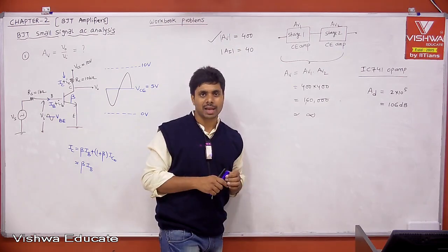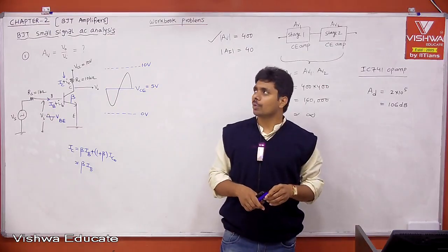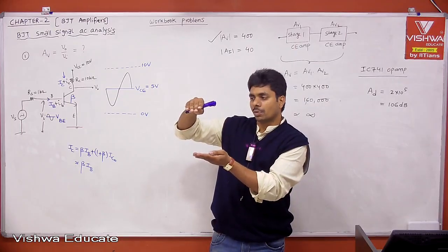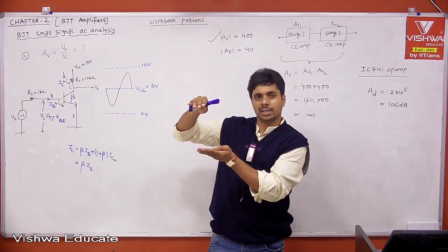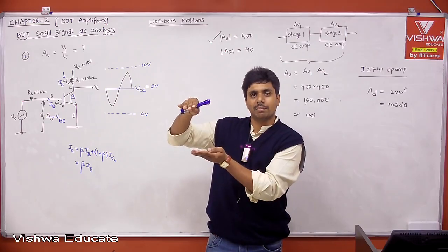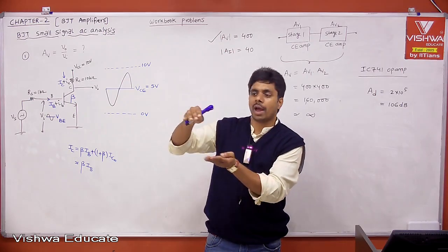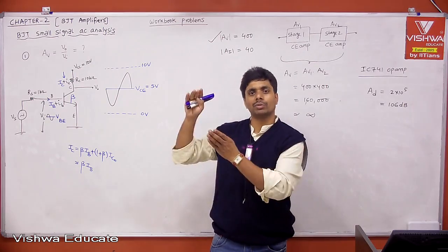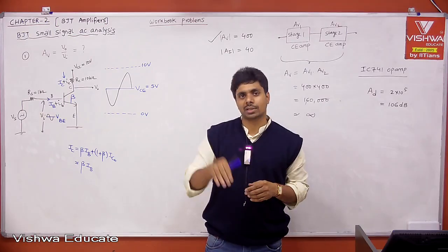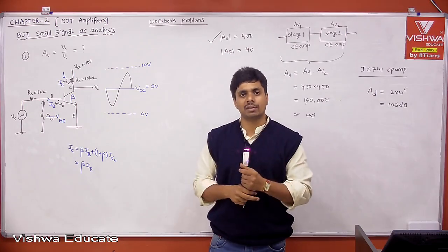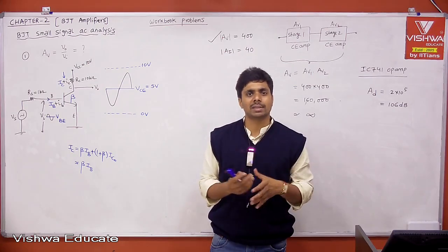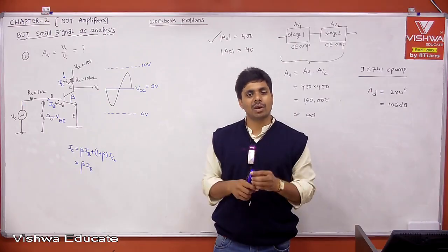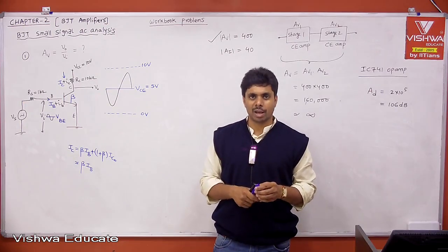Let me give you a small practical example. Remember, the power supply we get for our home applications is 230 volt RMS. That is nothing but an AC signal of 230 volt RMS. Let us say you are giving that to a fan, an 80 watt fan. When we give 230 volt RMS, the current it takes to get the mechanical power of 80 watt is in the order of less than 1 ampere, right? It will be in the order of 0.4 ampere. Your current will be in the order of 0.4 ampere, 0.3 ampere, but the voltage will be AC voltage.